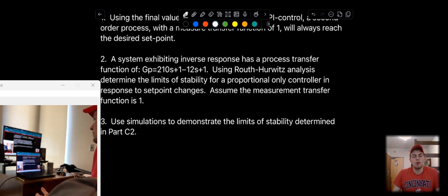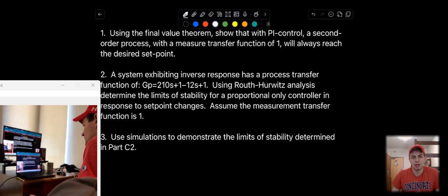In my last video, we discussed Routh-Hurwitz's criterion as a necessary means for developing an algorithm of stability for a given closed-loop transfer function. In this video, we're going to expand on that idea, first by proving that for a set point unit step change, we can always use an additional control parameter to minimize/eradicate offset in the system.